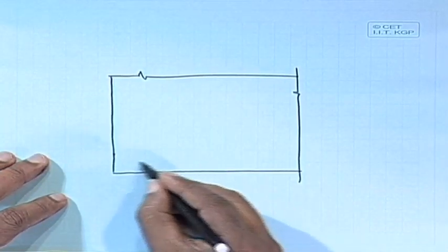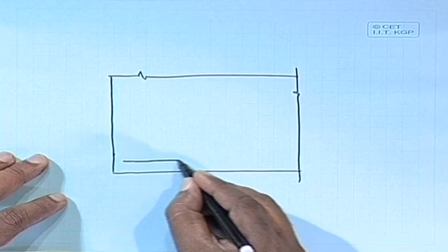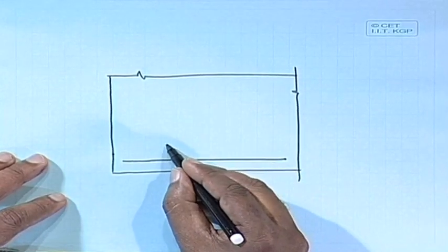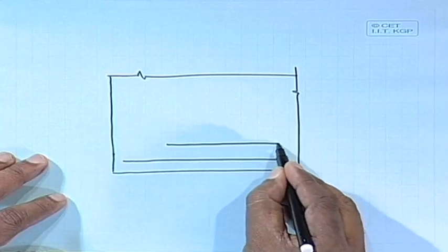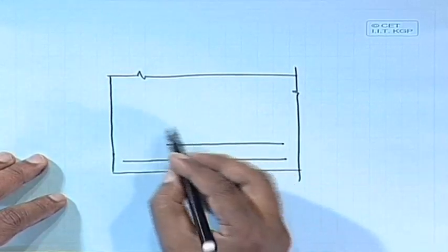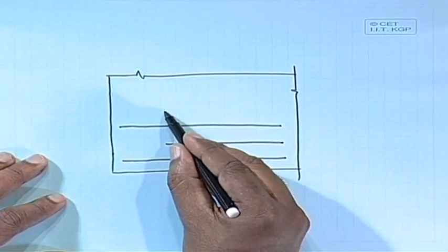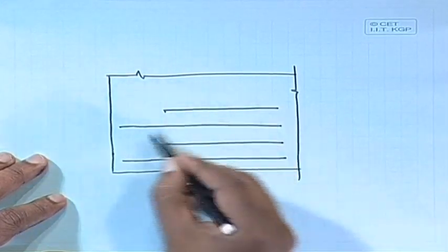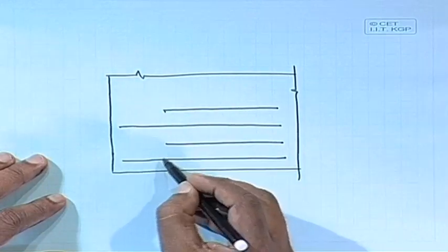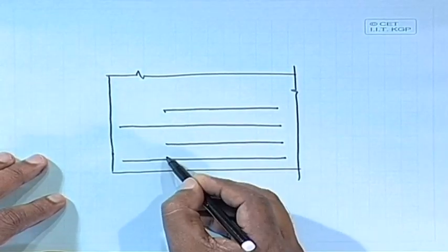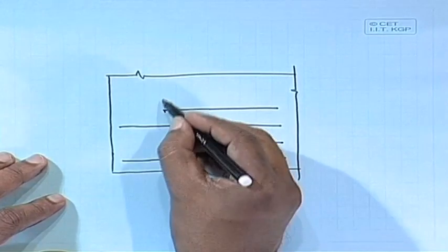So, say this is one bar in the bottom, the other bar we just simply cut it here, that is I am talking for the bottom. Similarly, another bar here, the other bar which is coming here, because we do not require that much of spacing at the bottom. So, here we can just curtail the bar. So, that is the idea.